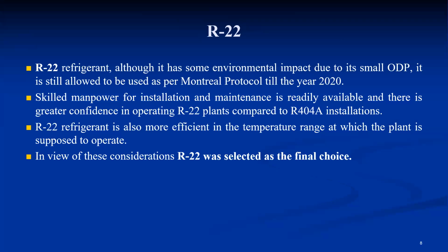There are 20 desirable properties of the ideal refrigerant, but a single refrigerant cannot possess all 20 properties. So the properties which are most suited to the given application are first listed out, and then the best possible refrigerant to meet these properties is selected.